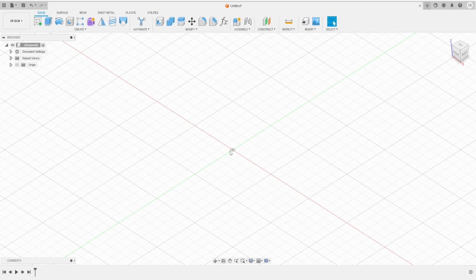Luckily for you, you are a smart designer, so as soon as you started the project, you created parameters for each one of the steps your design will have. This way, you can now go to the parameters and change the measurement of the circle directly there, and your whole design will now adapt to it. It's a pretty powerful tool, right?